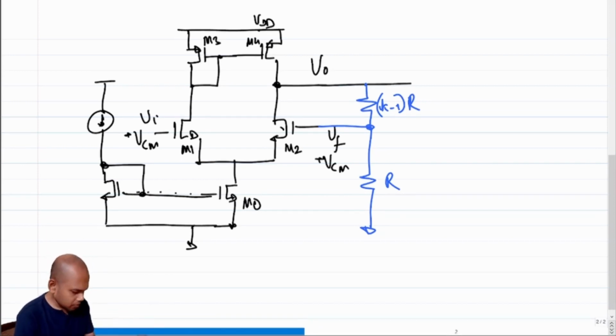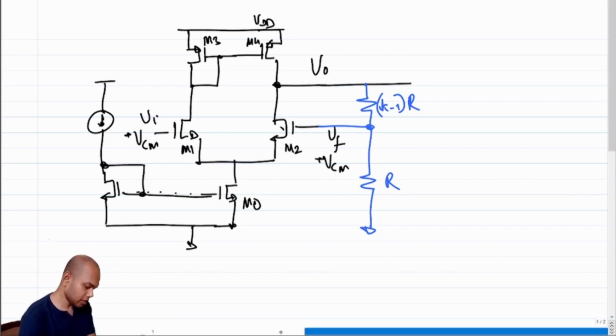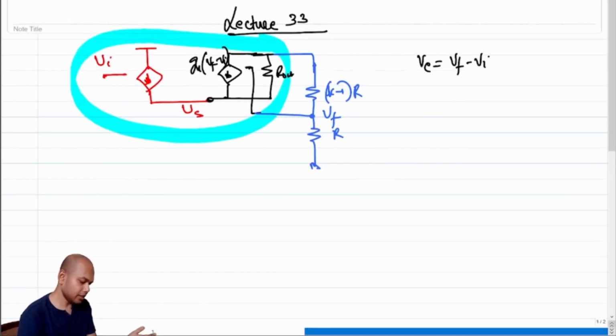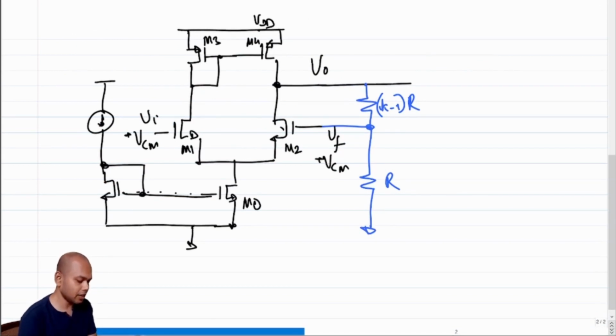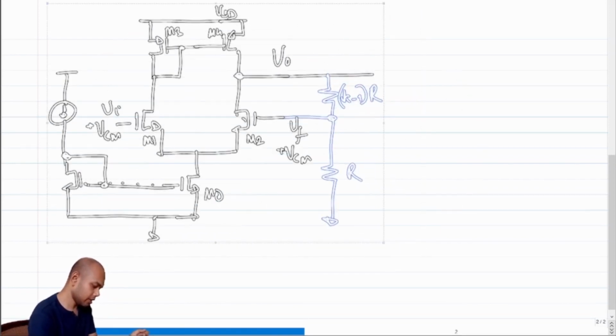Okay, fine. So do you see the relation? Do you see the similarity between this structure and this structure? So the structure that we have in this page is essentially a very rudimentary small signal equivalent of this structure. But now we know the differential amplifier. A differential amplifier has an equivalent GM and equivalent output impedance, and we can then replace this differential amplifier with its overall small signal model, and that would have been what?